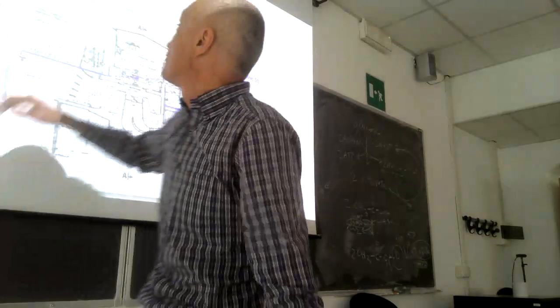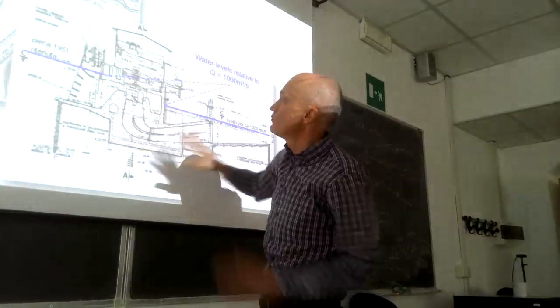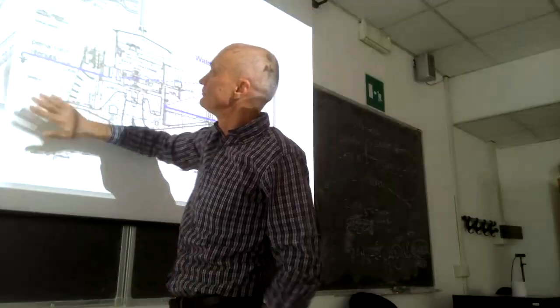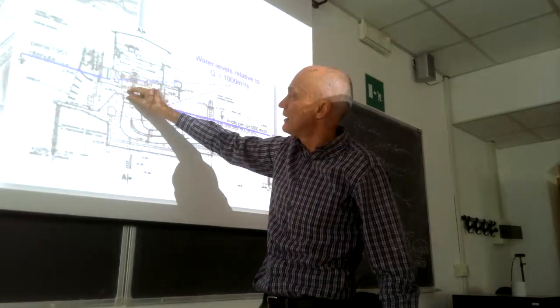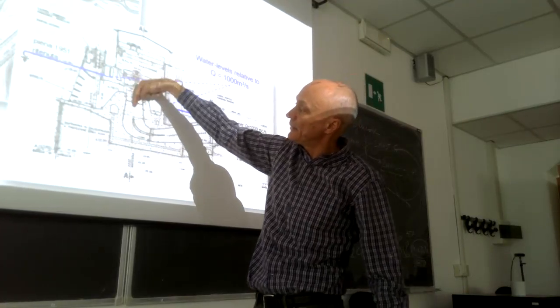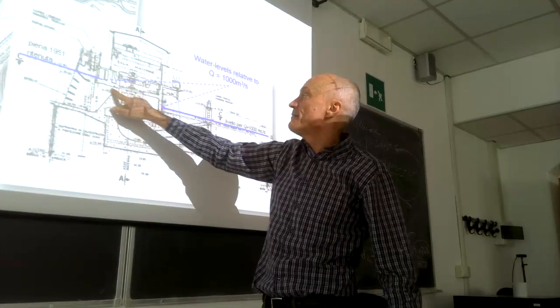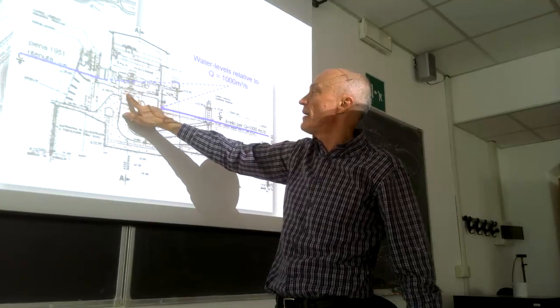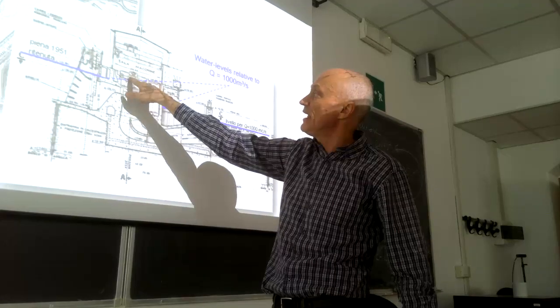The water flowing in makes the turbine spin and the generator spin, which produces electric energy. Then the water gets here, tailwater. The elevation difference between tailwater and intake is the effective hydraulic head, that is, what you convert into electric energy.